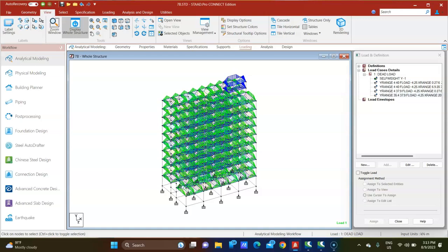Yeah, no, staircase load you will have to calculate, machine room also. Same method, machine room also you will have to first pick up the node coordinates. You put it accordingly. I am not repeating. Right? Next is how to assign the self weight of your wall. Right?